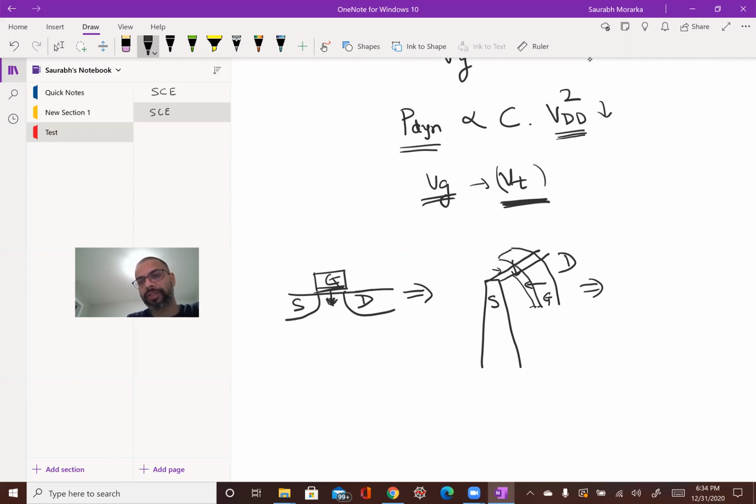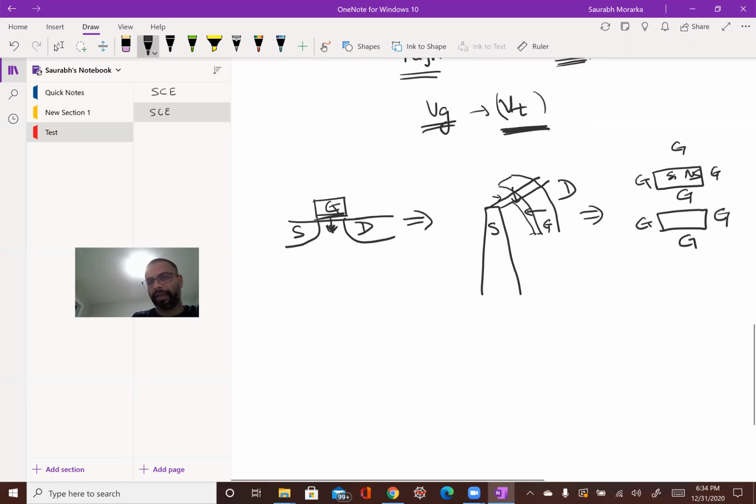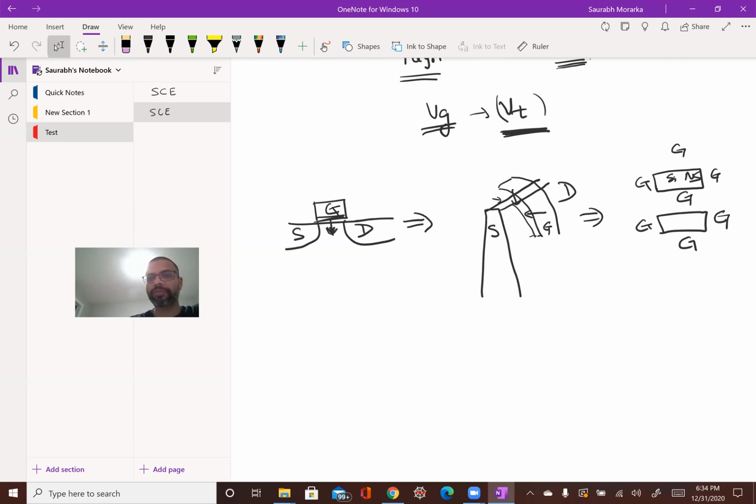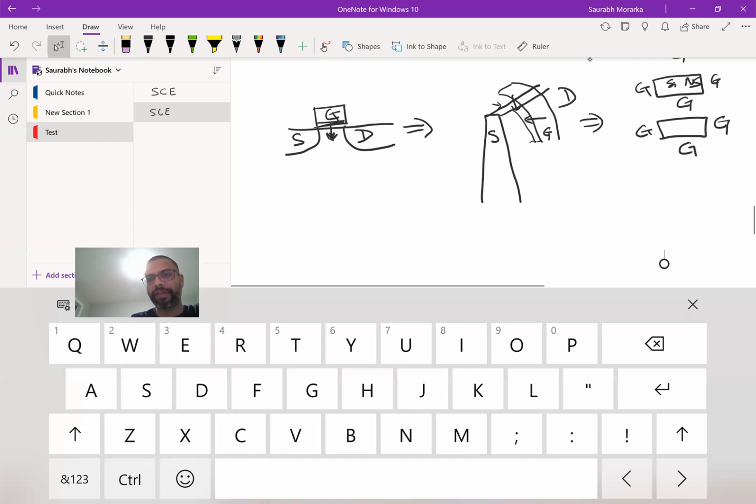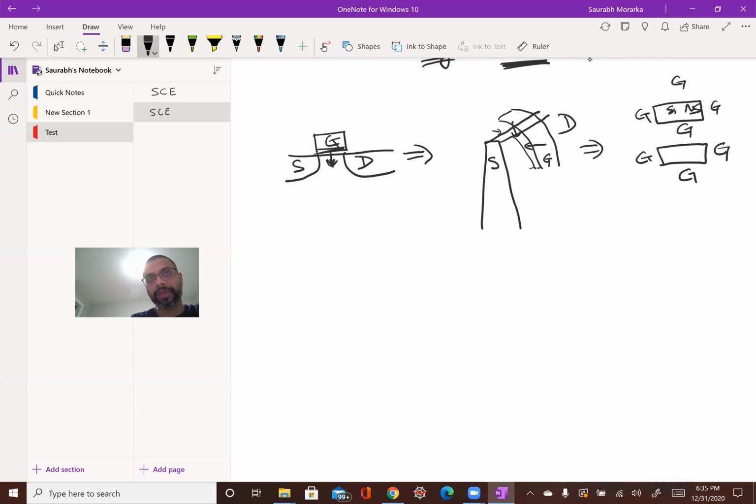And this has morphed into the all-sided gate control, which is also called the nanosheet. So this would be, say, the silicon nanosheet, and the gate would be all around that transistor, right? So that's how the technology has been evolving from planar transistor to the FinFET to the gate all around. And the biggest reason is to be able to control these short channel effects from going bad when the gate length is shrunk, correct?